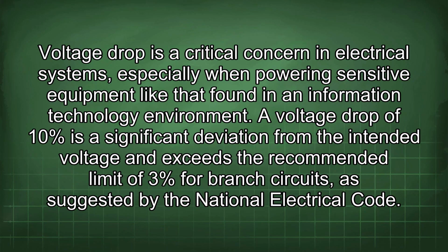Voltage drop is a critical concern in electrical systems, especially when powering sensitive equipment like that found in an information technology environment. A voltage drop of 10% is a significant deviation from the intended voltage and exceeds the recommended limit of 3% for branch circuits, as suggested by the National Electrical Code.